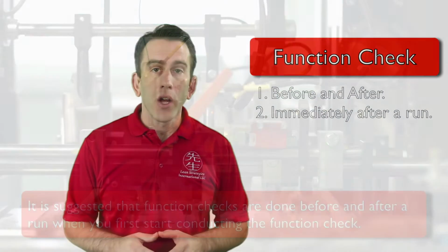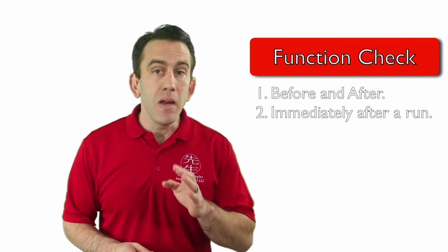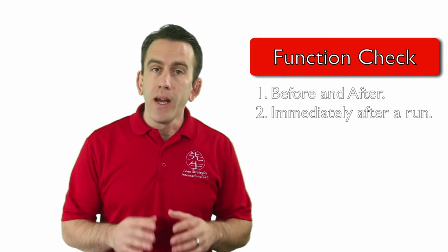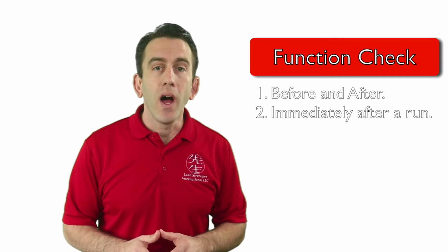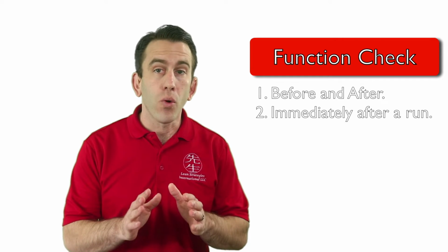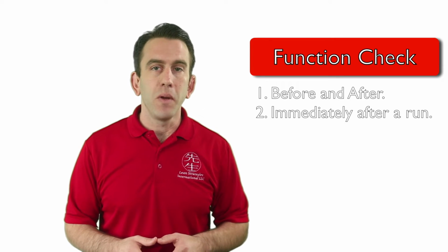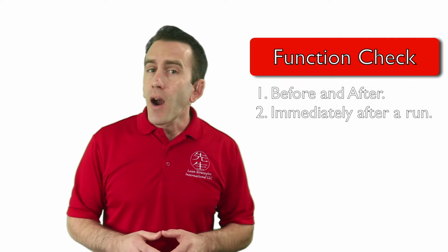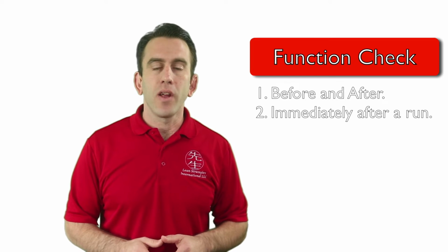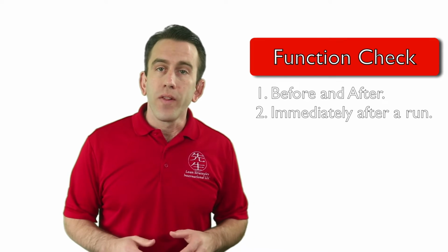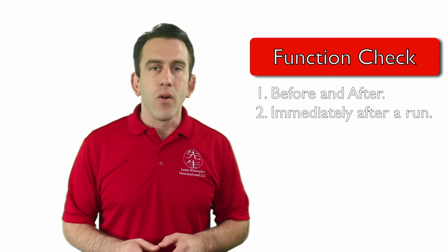Once you have your function checks occurring on a schedule, many organizations will perform the check immediately after a run. This way, if tooling, materials, or information needs to be corrected, it can be done well in advance of the next run and stored safely so that it is in working order for the next time it needs to be used. If it is not practical for you to advance to a functional test immediately after the setup is broken down, then ensure they are done well in advance of your changeover so as to minimize any downtime.